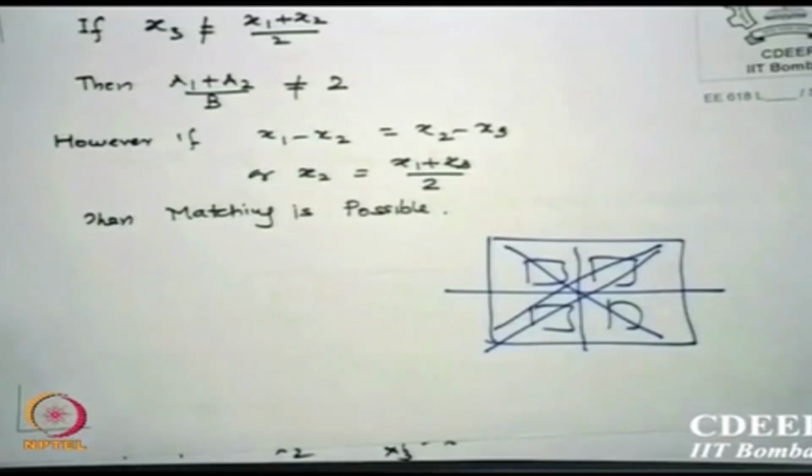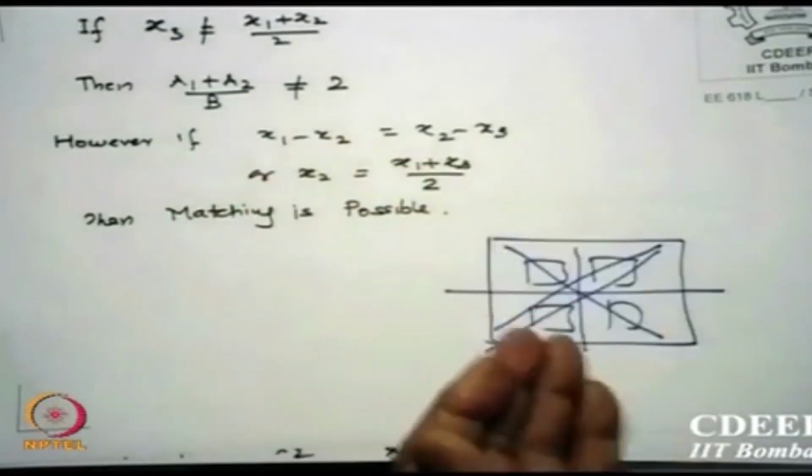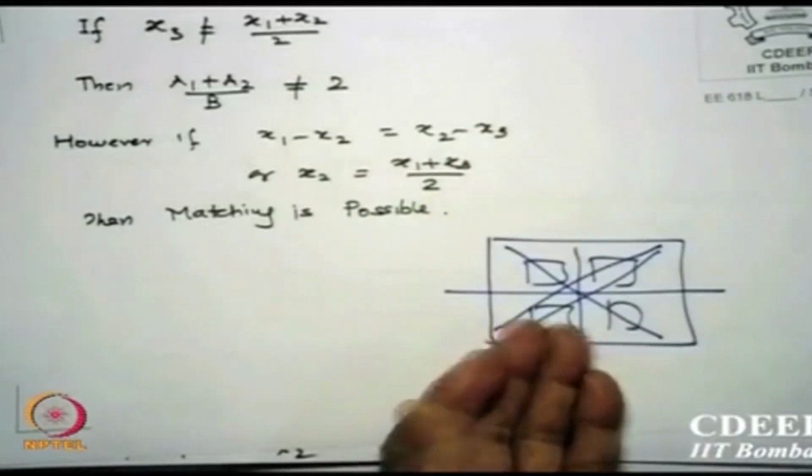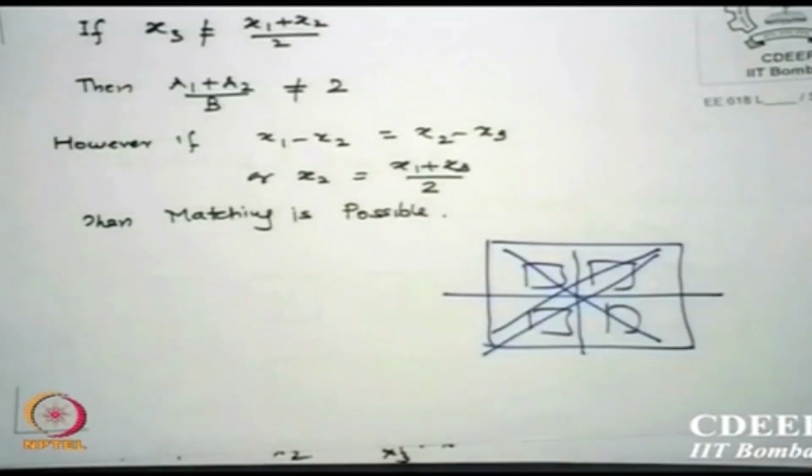Okay, so let us say there is a variation here, this is A1B for example, the opposite will appear here. If I connect them, then variation in the two is getting cancelled. Is that clear? So I always do common centroid, breaking into blocks so that the effectiveness of variation can be cancelled or at least minimized.